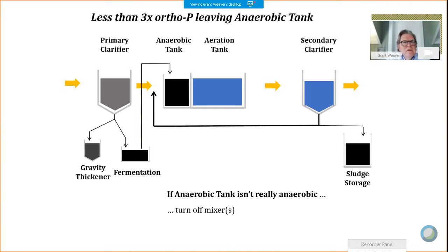Allow solids to settle. More counterintuitive. We're not supposed to let settling happen. But now, on purpose, we're going to allow solids to settle in the bottom of this tank. What's going to happen? It's going to become more anaerobic in that tank. Certainly down in the sludge blanket. And then maybe even put an elbow or chimney, a drop, to divert the flow down into that sludge blanket.